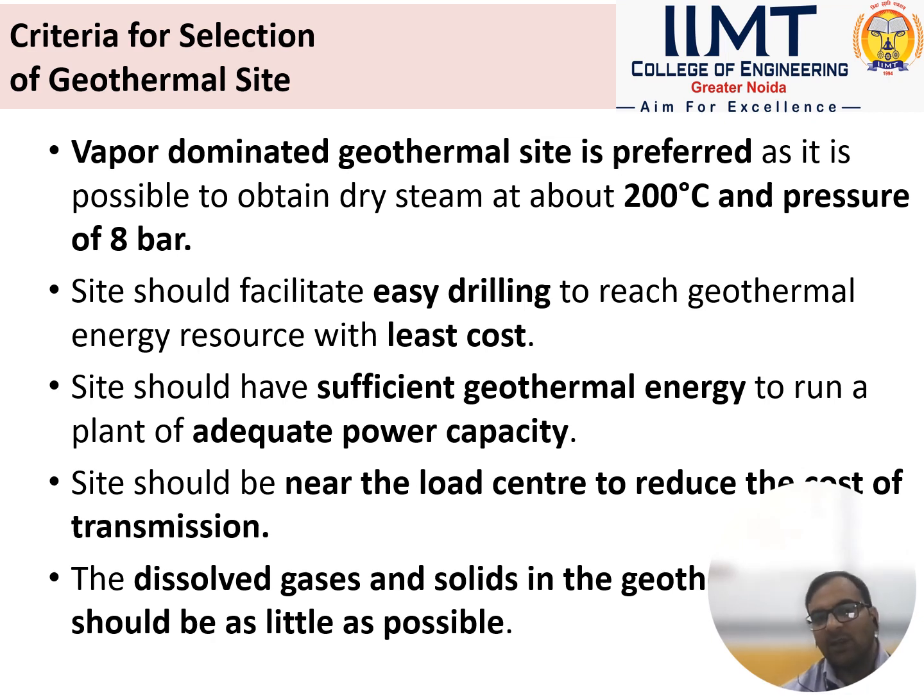To select the geothermal site, we have to consider these factors. Drilling should be easy, and cost should be as low as possible. Geothermal energy should be sufficient so that we can get adequate power capacity. Otherwise, there will be huge investment and we won't get sufficient energy, so that will be of no use. And it should be near the load sector to reduce the cost of transmission. If villages or cities are near the geothermal site, the transmission cost will not be that high.